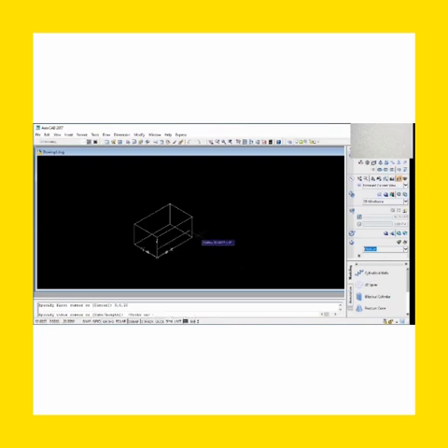So now specify the length. You have the option of keyboard length, so you choose a length. Since we are choosing length, you type L, enter. And now let's take a length of 70. We have 70 and then enter. And then the width is 64. 64 is already there, so we press enter. While the height is 30, so now you type 30 and then enter.